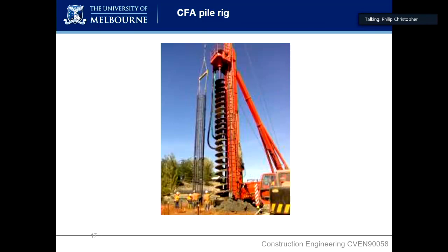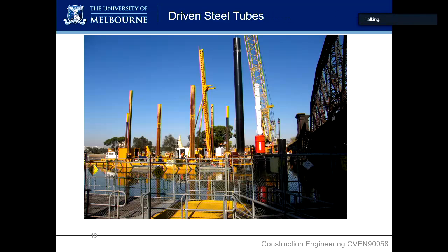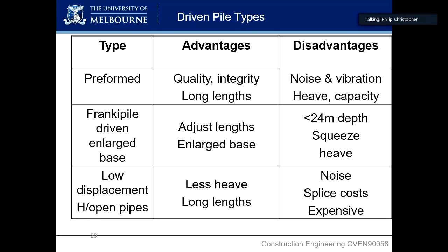Here's another giant rig, that's a particularly big one. Here's some examples on a bridge abutment. You see lots of alluvial, great application for a CFA pile. Some more steel tubes in a marine application driven into the ground, and again you would excavate the material in those tubes.